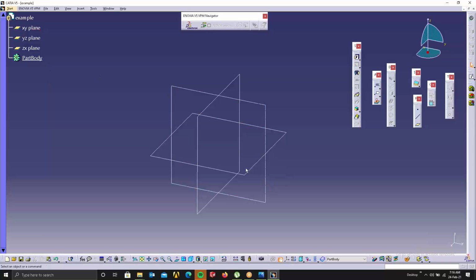At the same time, if you just create sharp edges and use the fillet option from the Part Design workbench, then in the specification tree you'll get the value. Double click on the value, change the fillet, and you're good to go. That is how you should think. Simplification means that, not doubling the work. I wanted to clarify that so you guys don't get confused.